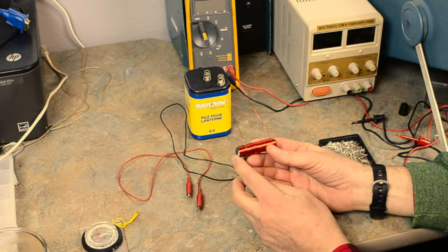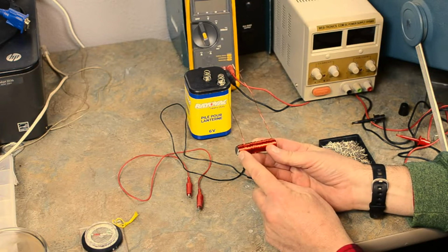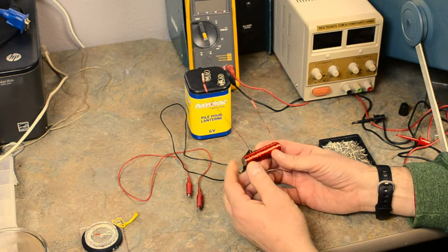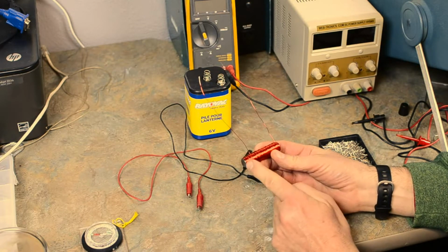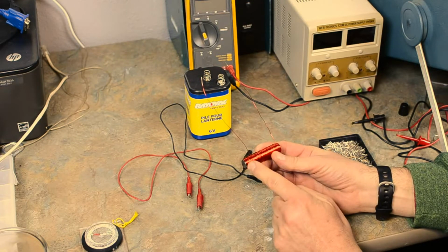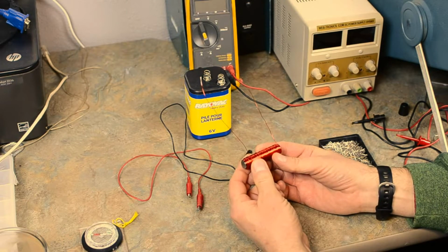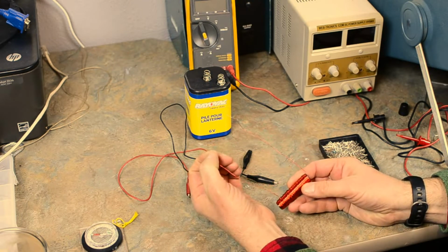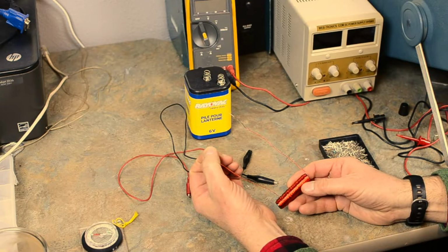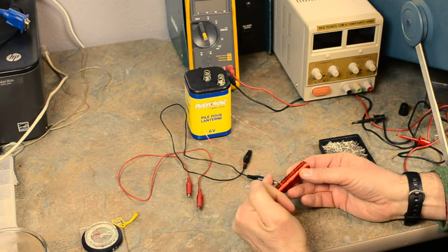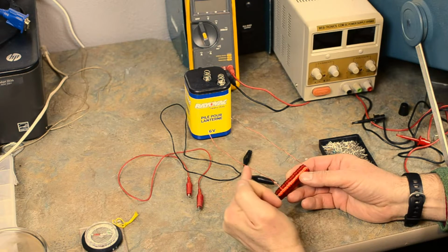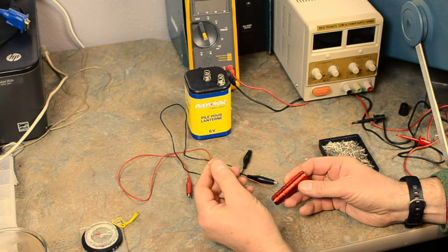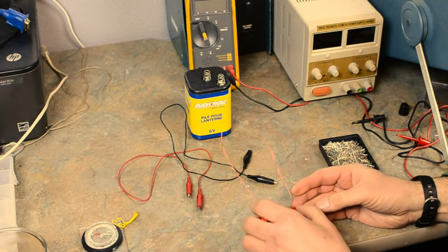I wrapped it with electrical tape, and then I wrapped it with this magnetic wire. Some people call it motor winding wire. And I wound it all the way down, all the way back, and all the way down again. So there's 3 layers of magnetic wire on here. And then I just cleaned off the ends of the magnetic wire to make good electrical connections. This red coating is actually insulation. It's very thin. It didn't take much to clean it off, but to make my electrical connections, I needed to